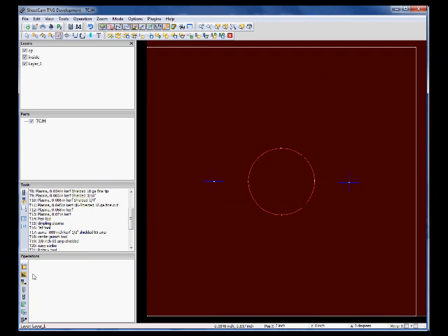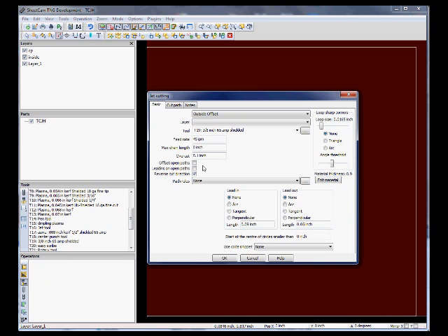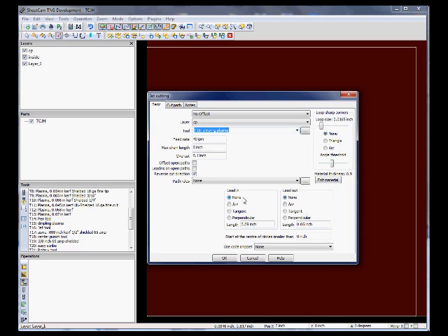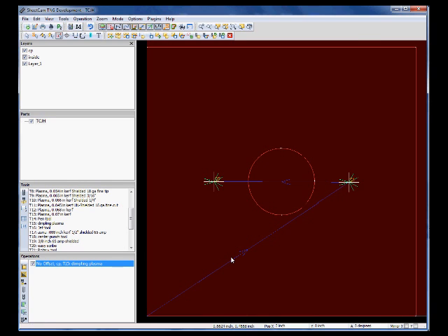So we close that. We come down here and click on plasma. We are going to do no offset. We are going to do layer, which is center punch. We are going to select the tool, which was dimpling, and feed rate and so forth. As long as you don't have any lead in and lead outs, there's no problem with it. So you click on it.